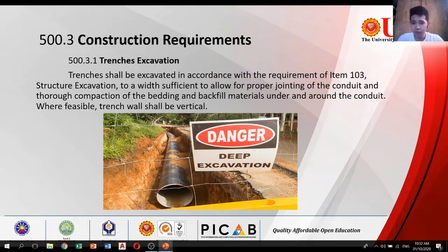So, trench excavation. Trenches shall be excavated in accordance with the requirement of item 103, structure excavation, to a width sufficient to allow for proper jointing of the conduit and thorough compaction of bedding and backfill materials under and around the conduit.